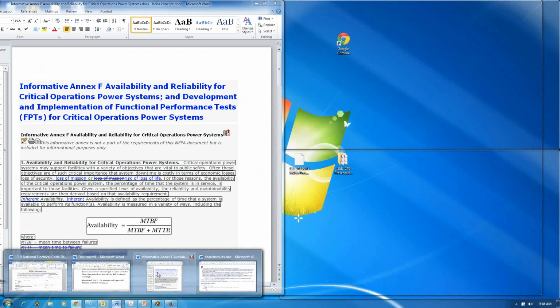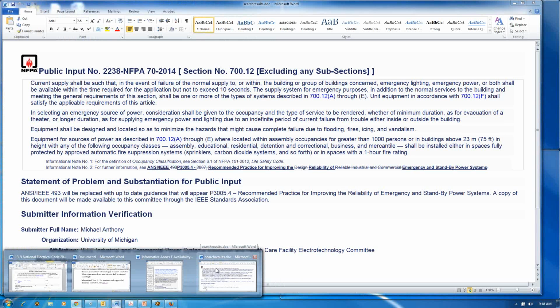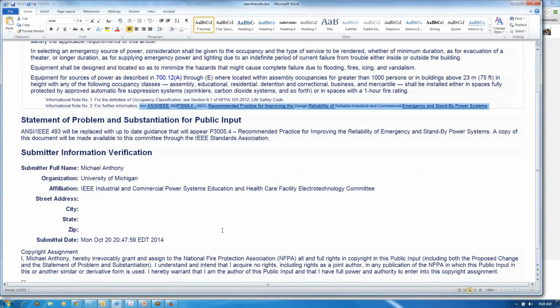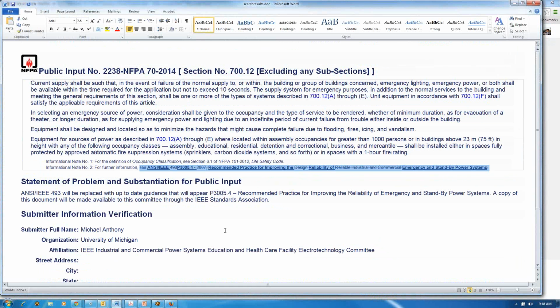So if there's a transmission system outage, I mean an area-wide blackout, both of the utility feeds fail because they're not supplied by their source, and the redundancy that you thought you were getting isn't there.